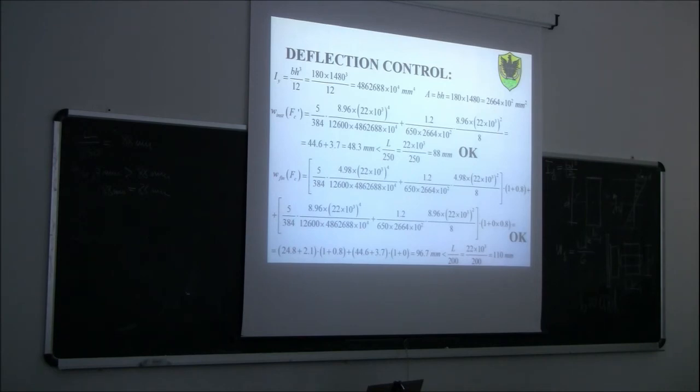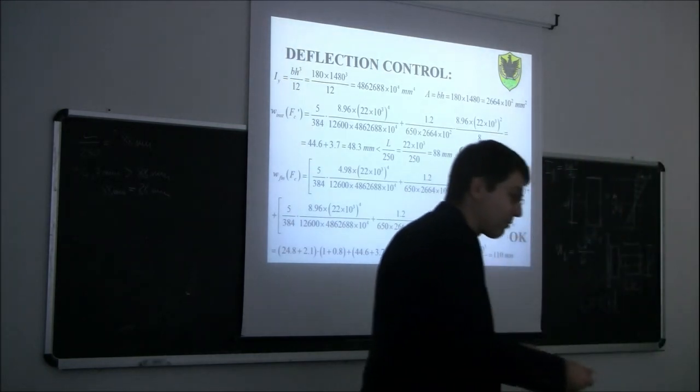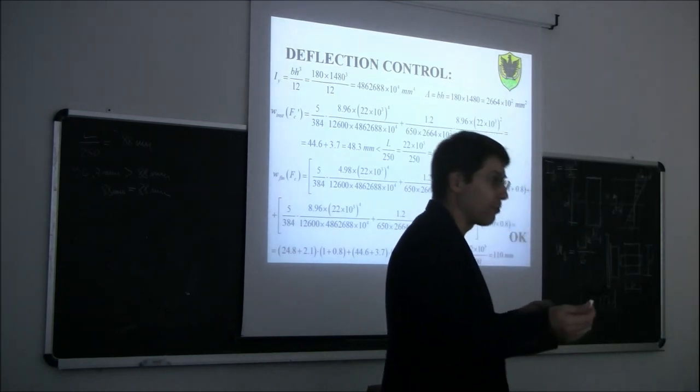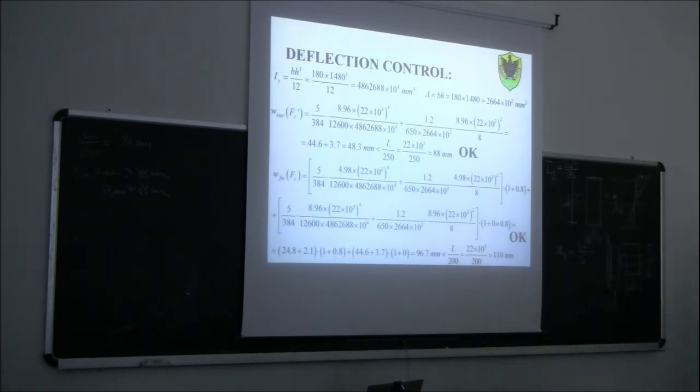Which, in terms of engineering, from the engineering point of view, to me, 89 millimeters or 88 is exactly the same, because there are so many uncertainties in calculating the creep coefficient and the modulus that is really there. But of course, since you have to submit this report to an authority, you need to be careful. So you need to avoid this kind of verification which is substantially satisfied but formally not satisfied. So in this case it would be better to reassess the self weight and to increase the breadth a little bit more.